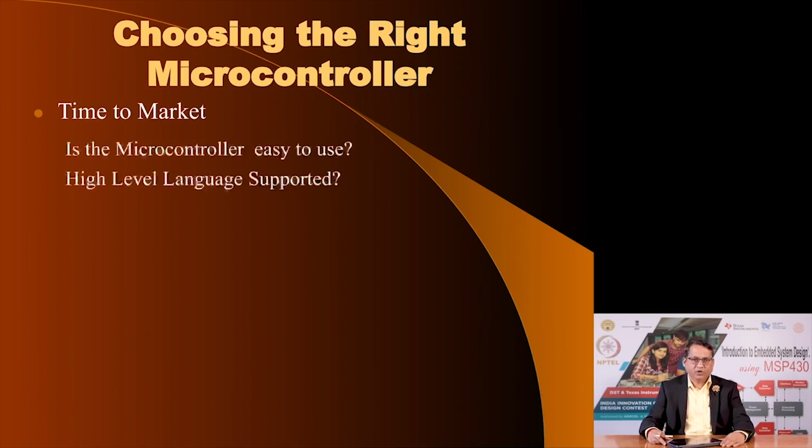Usually these days people do not use assembly language programs, they prefer C or C++, and there are many other languages which are being used for programming microcontrollers for embedded applications, and therefore, you as a designer must find out whether the language of your choice is supported through various software tools for the microcontroller that you want to use. If not, it will impact time to market.